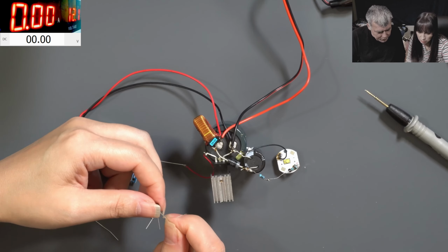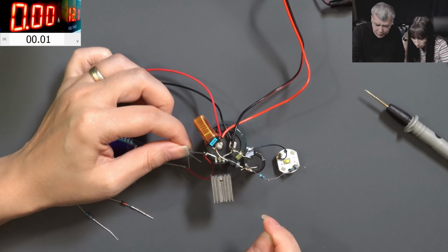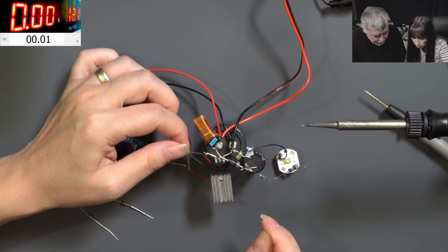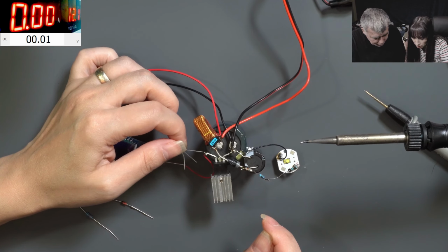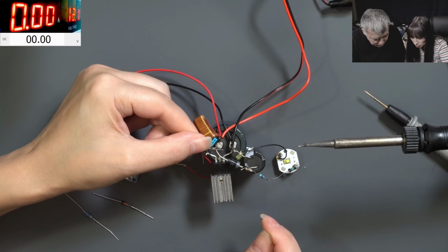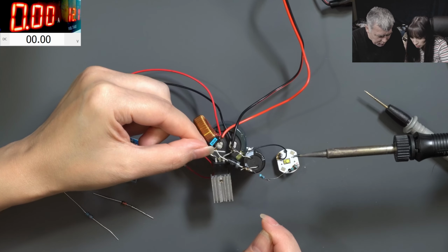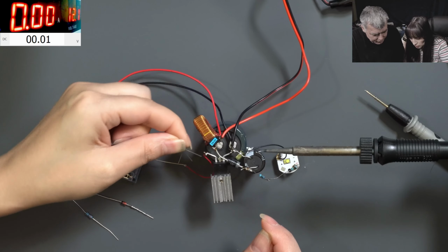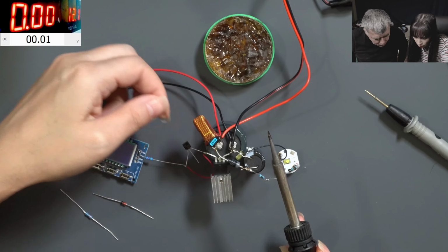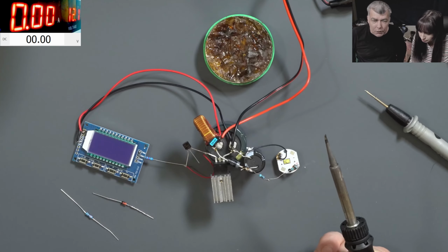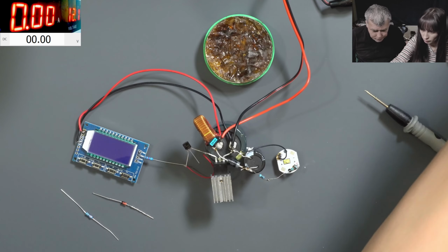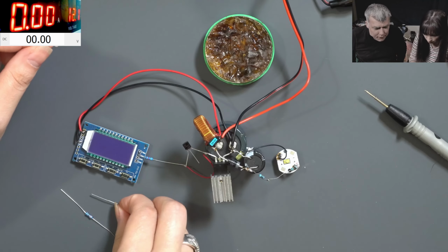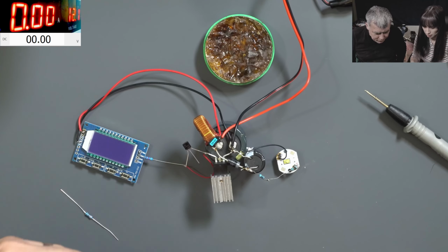So the drain has to be soldered to the gate. Yeah, do it. But wait a second. And the other one should be like this. We can use a wire for that. It's risky to connect the transistor over the diode. So I should put it like this? Good. Now solder the Zener diode. Give me the schematic.